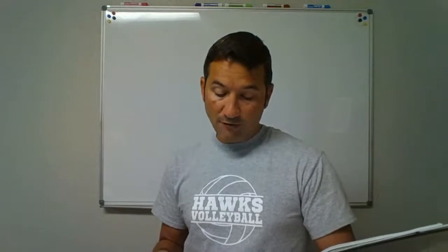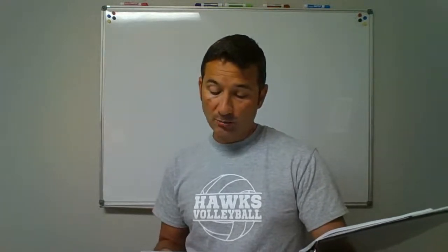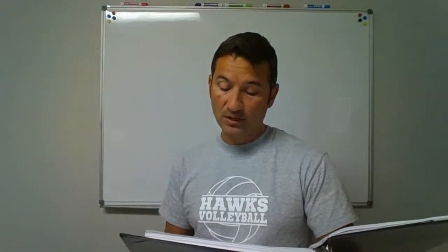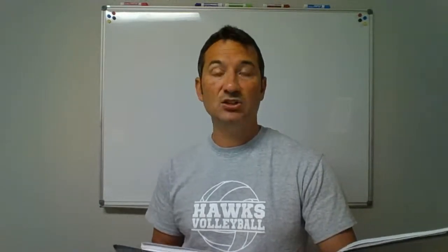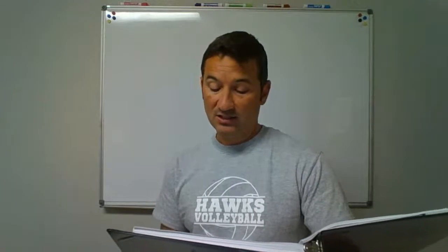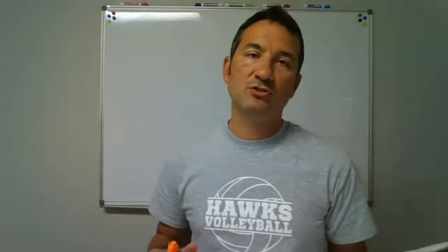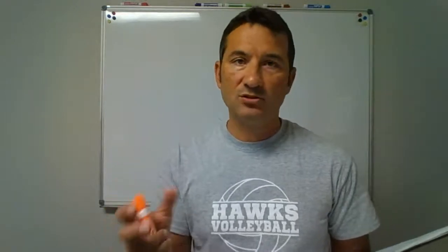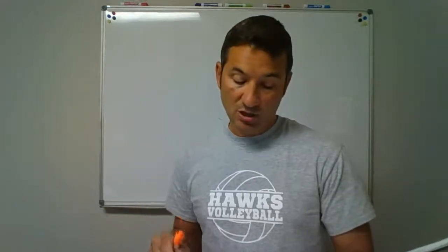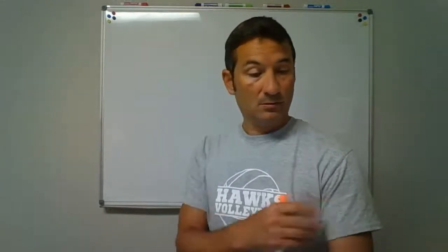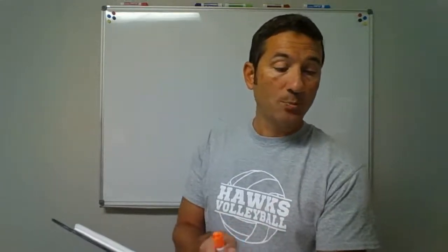Strainer plates, 304.2. All strainer plates on drain inlets shall be designed and installed so that the openings are not greater than a half an inch in least dimension. Most of the time you're just buying a strainer plate and trusting that the manufacturer made the openings less than a half an inch, but that's where the code states that.